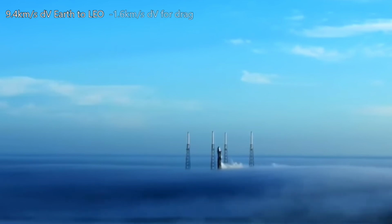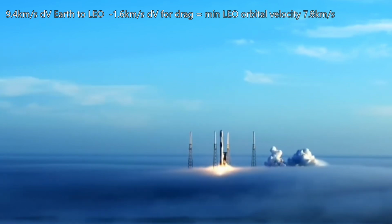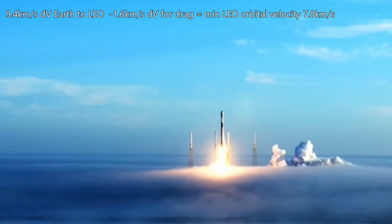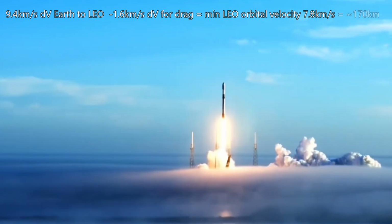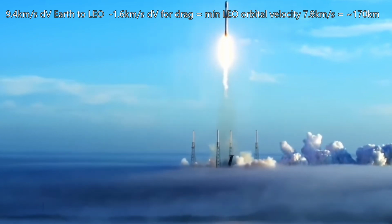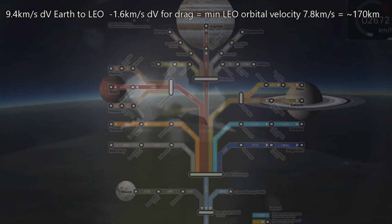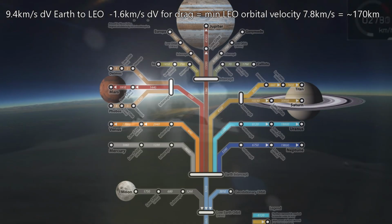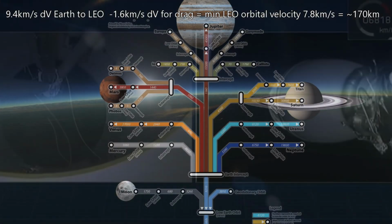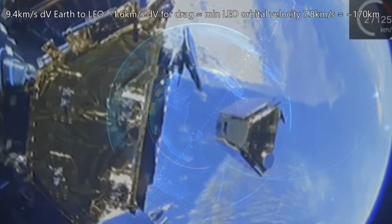Subtracting the gravity drag and air resistance will get us to a low Earth orbit with an orbital velocity of about 7,800 meters per second. This would be an orbital altitude of about 170 kilometers. That's very low, and your spacecraft or satellite would experience a lot of atmospheric drag, but you don't have to stay there. Once in LEO, you can budget to go wherever you want, to a higher, more stable orbit, or elsewhere if you calculated enough delta V.